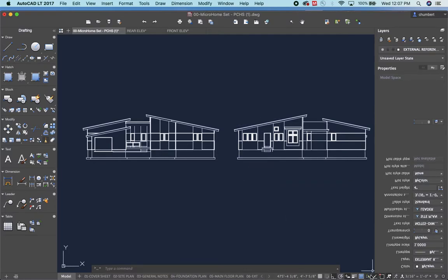Okay, other snaps that you have down here, this one I use a lot. This is the snap to objects. Okay, so that's how you can get it to either, like, if I go enter, P, enter, enter, it snaps to the corners. See that? If I uncheck that box, then it doesn't snap to the corners. It just kind of moves around. So you almost always want it to snap. And you know it's active because it's turning dark. So a couple tools right there that are super handy that you use a lot.